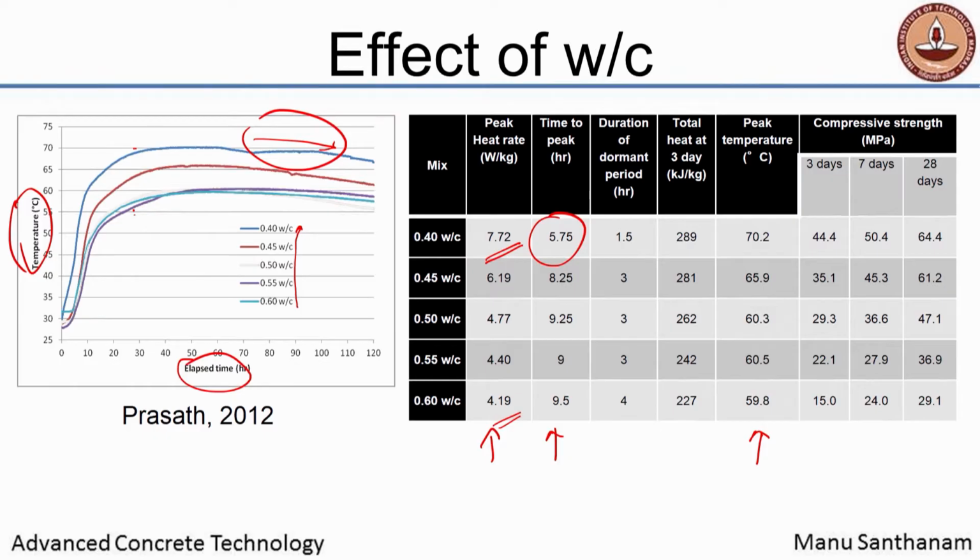Okay. So, needless to say, when you are working with high strength concretes, you need to pay particular attention to the choice of your concreting process to ensure that you are keeping in mind that your temperature rise can be significant in these systems, and you need to control the rate of temperature rise if it is critical in your concrete. For example, if you are designing very thin concrete structures, not a major issue, but if you are designing mass concrete where temperature differentials can be significant, this heat rise can create a lot of problems. I will show you some examples later.